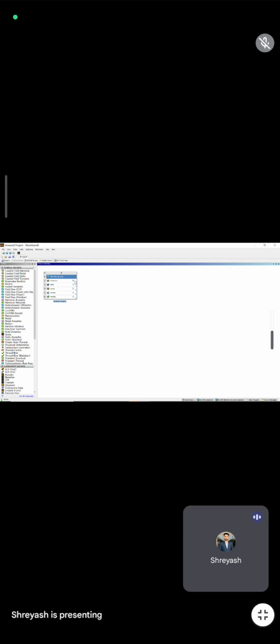Okay. So right click on the geometry. If you want to give a new name, you can just double click and give a name. Okay, like this. Now right click on geometry. You can see there are 3 options: the Discovery, the SpaceClaim, and the DesignModeler. Then there is one more option for import geometry. So if you have made your geometry in any other designing software, you can just directly import your geometry, right?